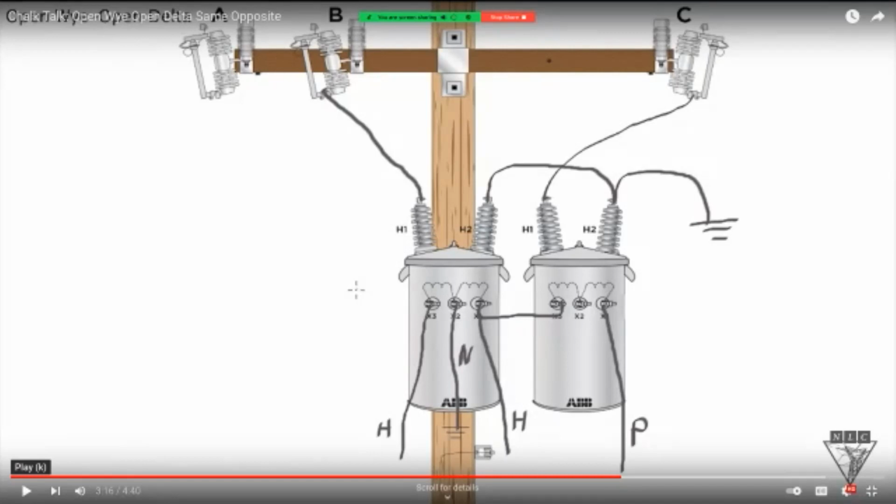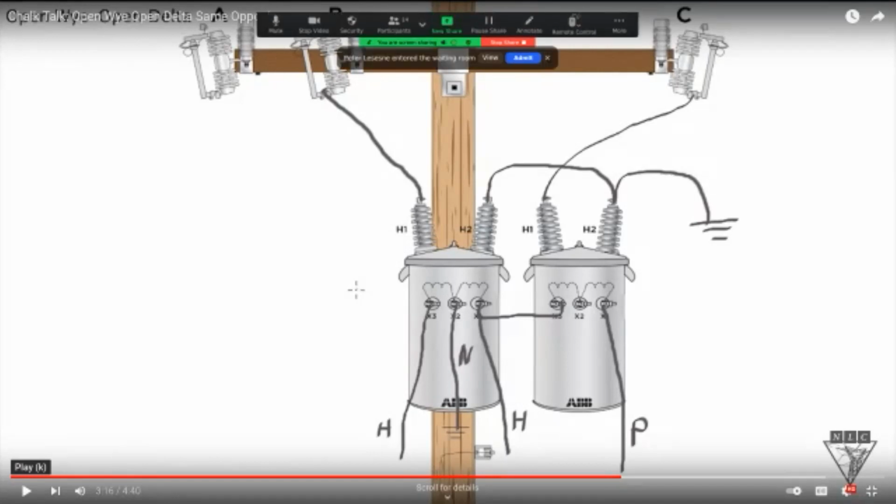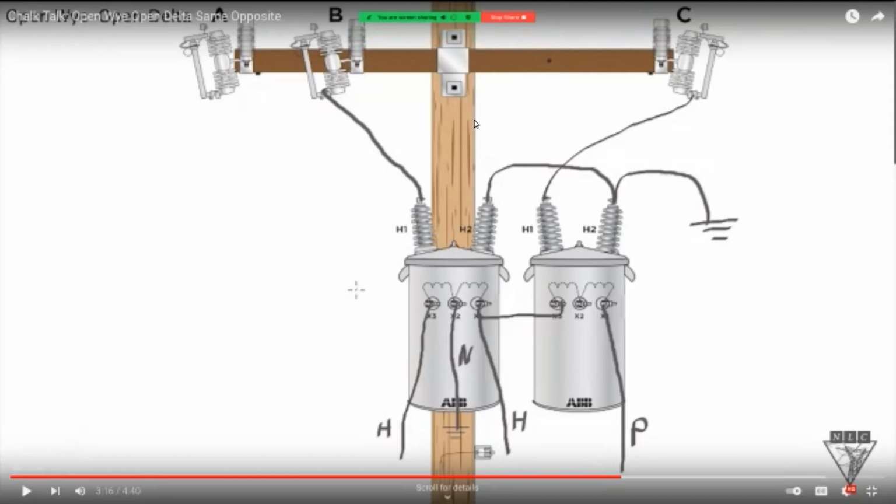Back in the 60s and early 70s, I don't know if you guys are aware of areas like Pine Lakes and the old parts of Myrtle Beach up there. A lot of the bigger homes up there did have 3-phase air conditioners. And there was a lot of open delta up there in those areas. That's because back in the old days of air conditioning, it was just the norm to have 3-phase air conditioning. Well, single-phase air conditioning came along, became much more efficient. And now 3-phase air conditioning for a single home is just not used as much anymore.